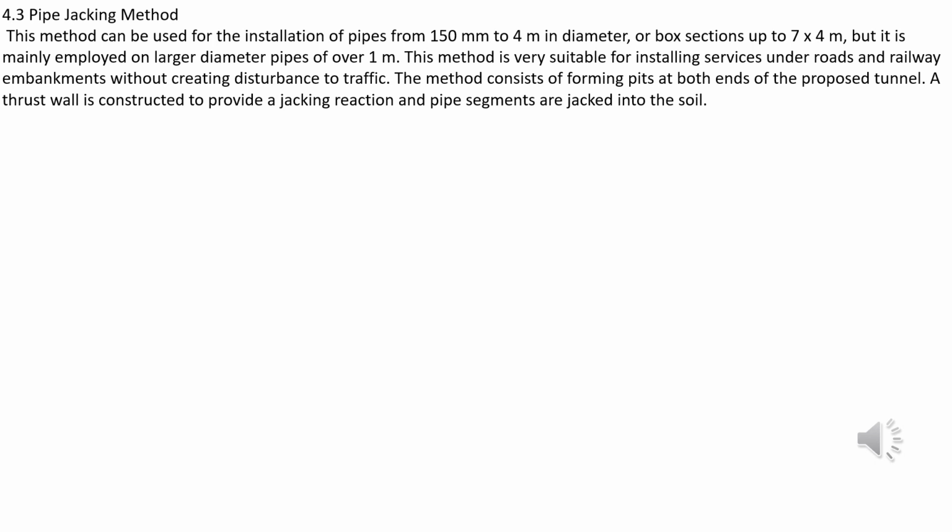The method consists of forming pits at both ends of the proposed tunnel. A thrust wall is constructed to provide jacking reaction, and the pipe segments are jacked into the side.